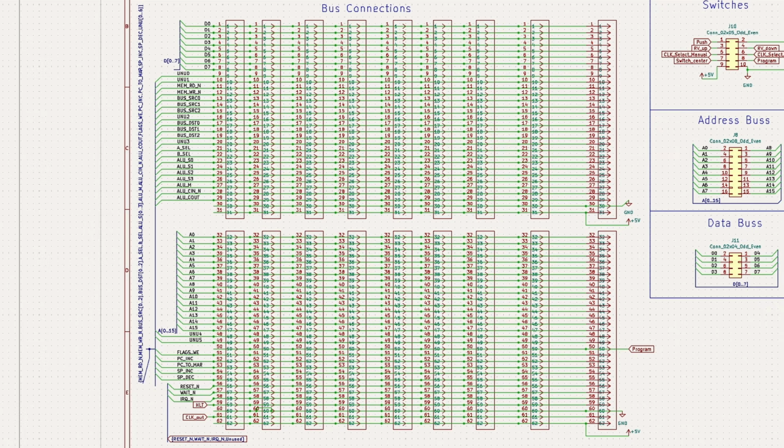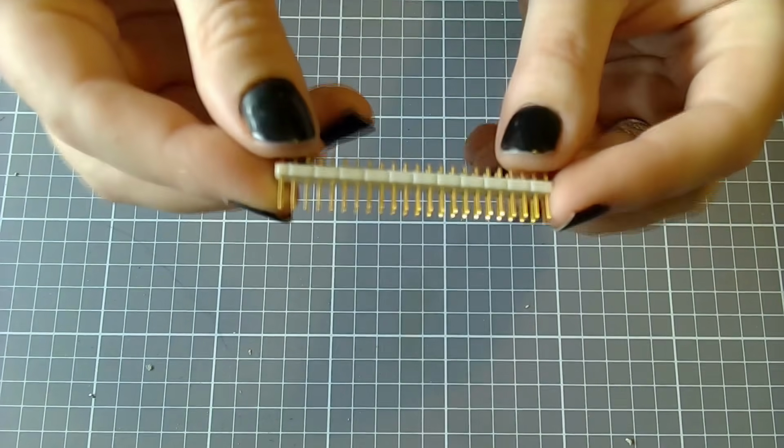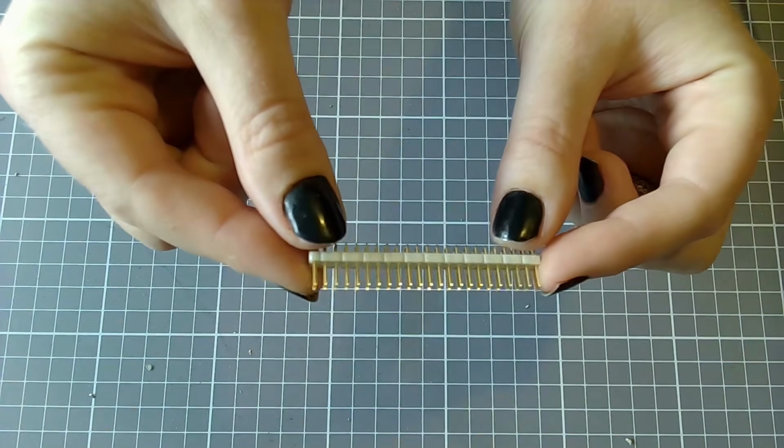Then there is this thing, a giant connector that dominates most of the schematic. At first, I thought I would use these pin header connectors to connect all of the modules to the backplane. However, I didn't really like the idea of having hundreds of these pin headers, since they could individually bend or break off. I just didn't know any better way to make these connections.